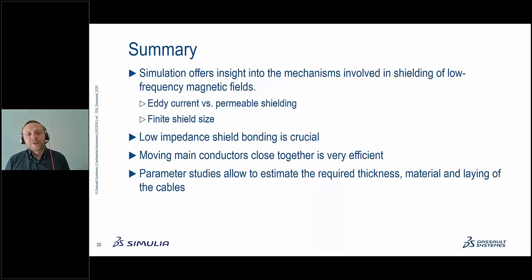Even so, you see, the models I have simulated are not that complex. It's basically just cables and the shield, but it gave me a lot of insight into what's actually happening and why I need the low impedance bonding, and whether moving the conductors is better or increasing the thickness of the shield. I can test all of these things using parameter studies.